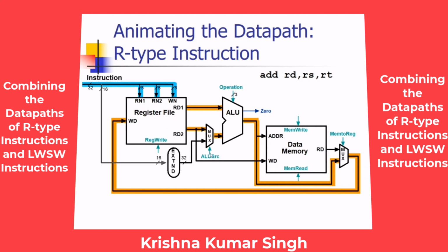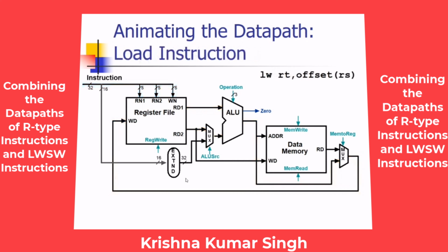So the highlighted parts indicate the part of the data path that is used by the R-type instruction. The control unit is responsible for assigning the corresponding values to ALUSource, MemtoReg, and the other signals in order to execute this instruction inside the processor.